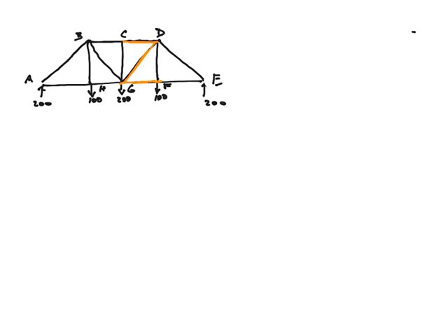Here is where the method of sections diverges away from what we did with the method of joints. Because I want these yellow members here, I've drawn CD, DG, and FG. Method of sections says if you could break your truss into two different pieces by drawing a line or making a cut or breaking the members of interest, that's what you should do.